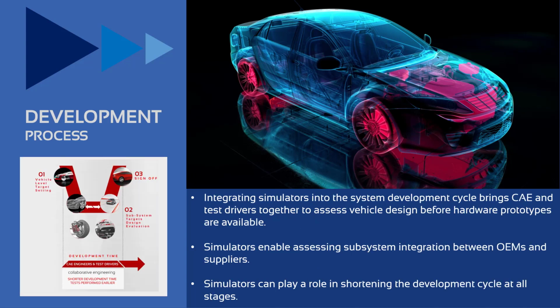With a shift from physical prototype and mule testing to a simulator-centric process, the role of the CAE team and the test drivers is brought closer together. This allows for more effective target setting by bringing the targets, as represented by the real-time model driven on the simulator, into a direct subjective evaluation during the target setting phase. To the extent that mule vehicles were used in the past to establish targets, they can be done with design intent models on the simulator.